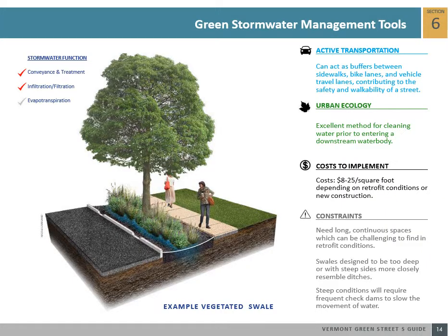Green gutters are very narrow landscape systems along street frontages that capture and slow stormwater flow. Typically less than 3 feet wide, green gutters resemble planters as they are confined by vertical curbs and have a flat bottom profile. Unlike typical planters, however, green gutters are designed to be flush with the street surface, are very shallow, and perform little or no water retention.